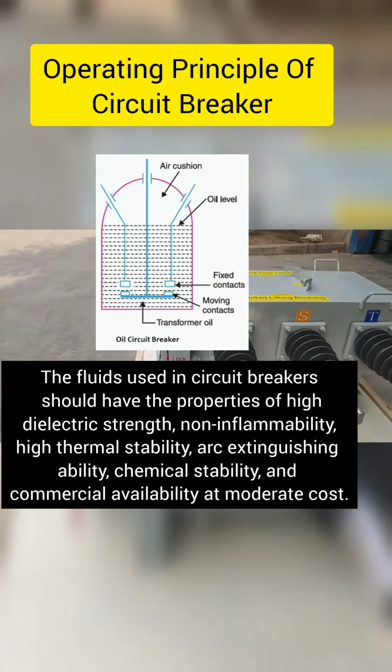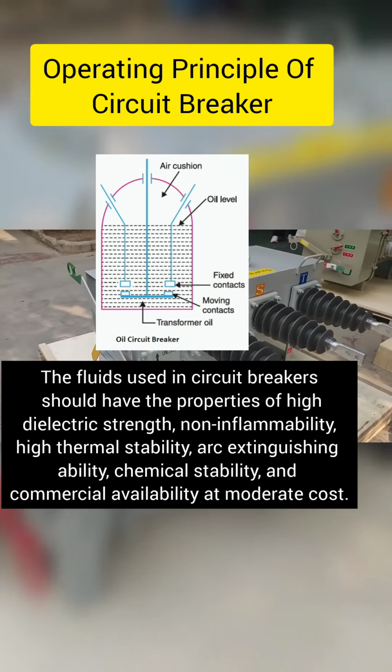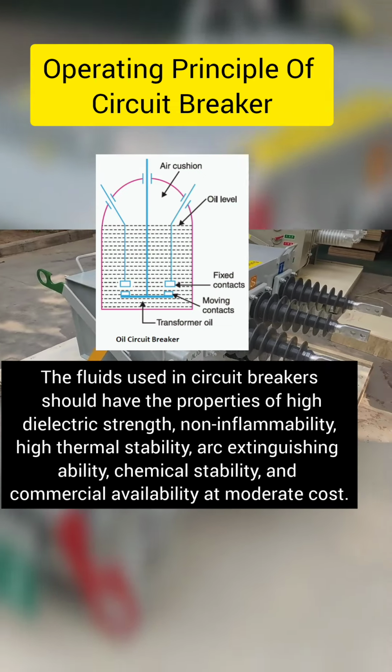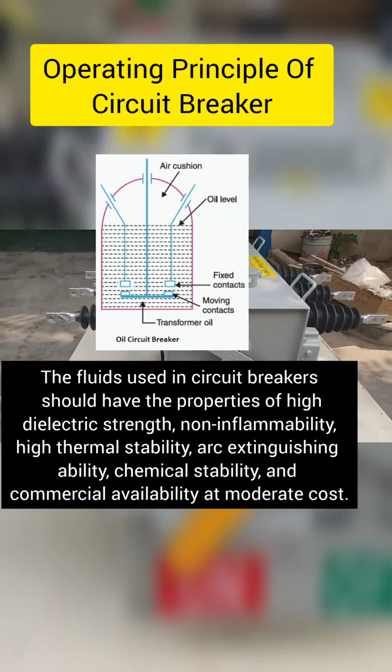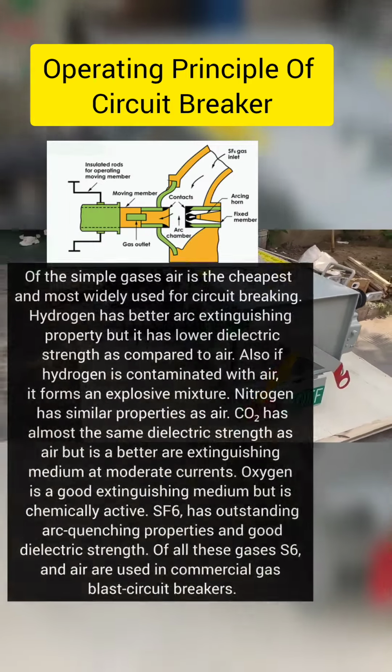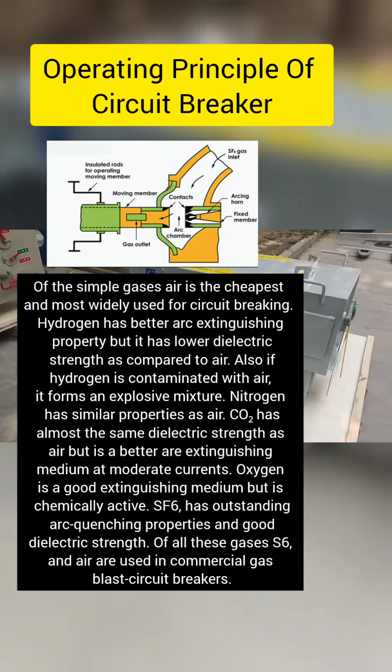The fluids used in circuit breakers should have the properties of high dielectric strength, non-inflammability, high thermal stability, arc extinguishing ability, chemical stability, and commercial availability at moderate cost. Of the simple gases, air is the cheapest and most widely used for circuit breaking.